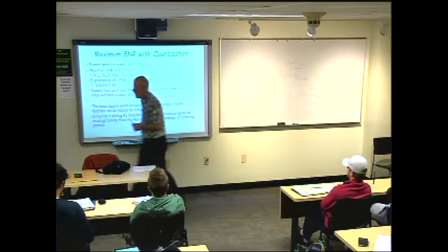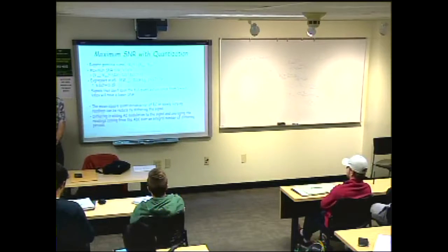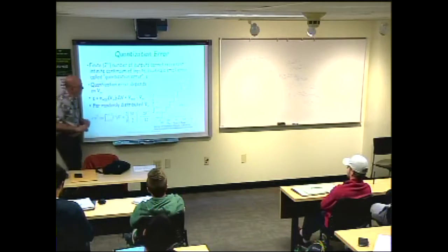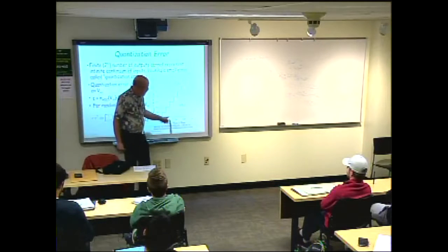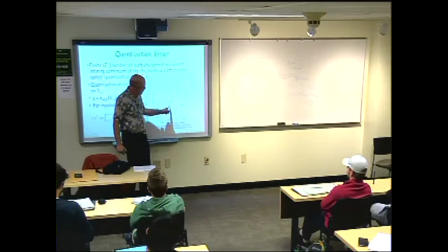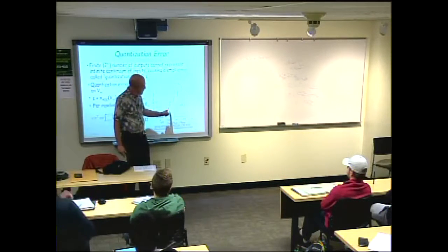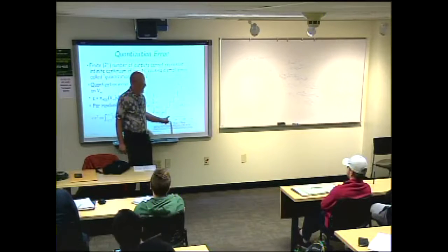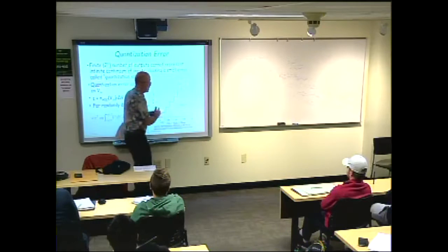Dithering is related to trying to stay out of bad spots in terms of quantization error. So if I was measuring just right at this blue signal, again, I would have a fairly high quantization error. I would actually be better off to take that signal and put a little bit of AC sinusoidal modulation on it and move it back and forth.